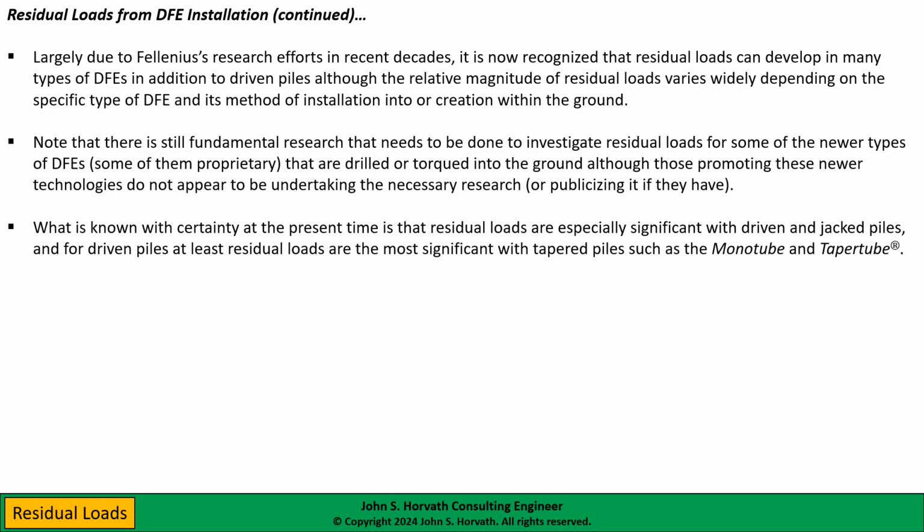What is known at present is that residual loads are especially significant with driven piles and jack piles. Jack piles are really not common here in the United States, as best as I can tell, but I do see them used at least in Asia to some extent. And for driven piles, at least, residual loads are most significant with tapered piles, such as the monotube and taper tube. And again, I'm going to be illustrating these things later with some case histories.